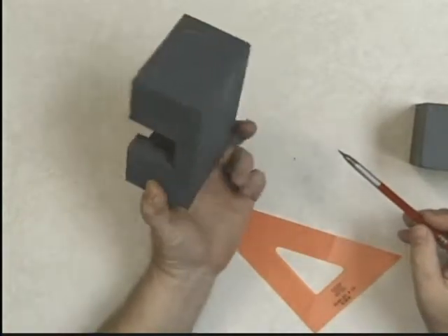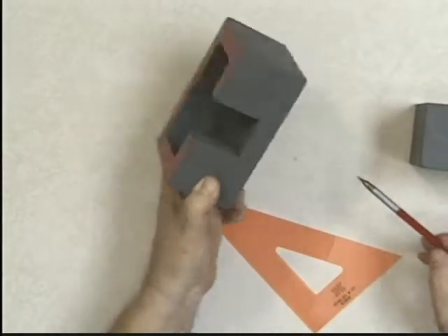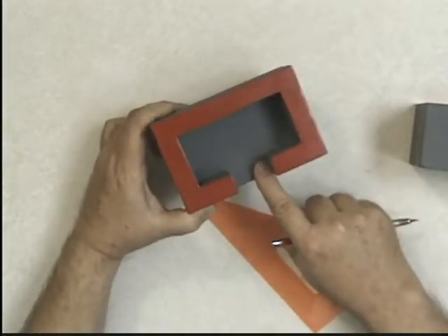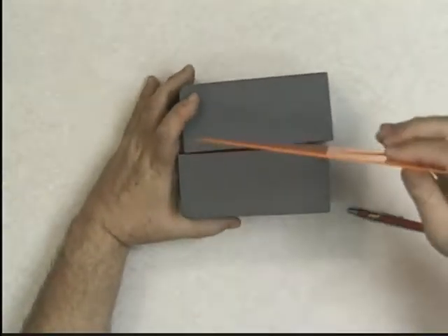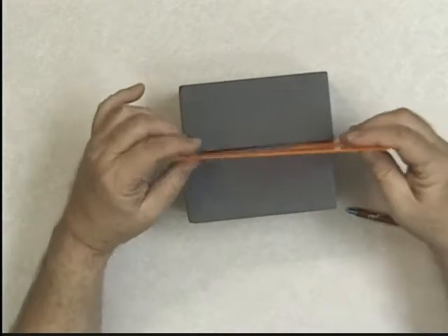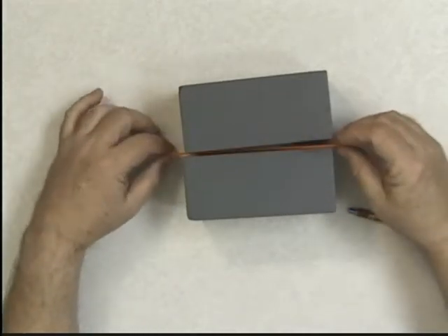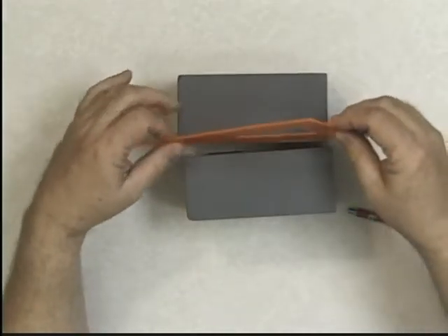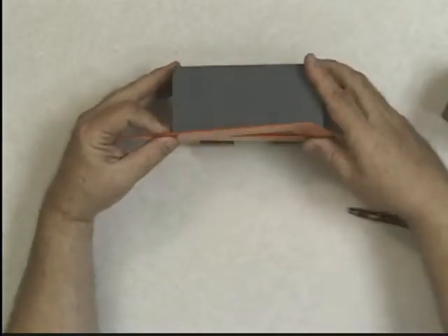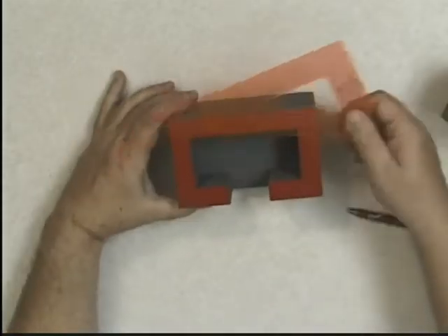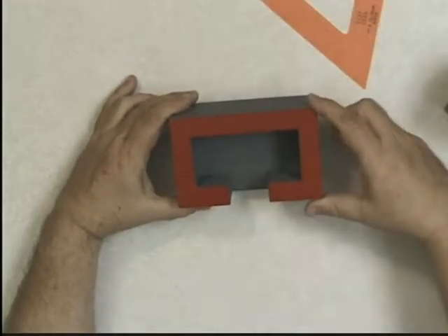See, it's flat on the back, but inside it comes down in here. So there's a little hole underneath. We wouldn't know that without cutting this open. So once again, to make the section view, we pass an imaginary cutting plane, and you can imagine the cutting plane with your triangle. We pass that cutting plane through, and we take away everything between you and the imaginary cutting plane and reveal the, in this case, full section of the object.